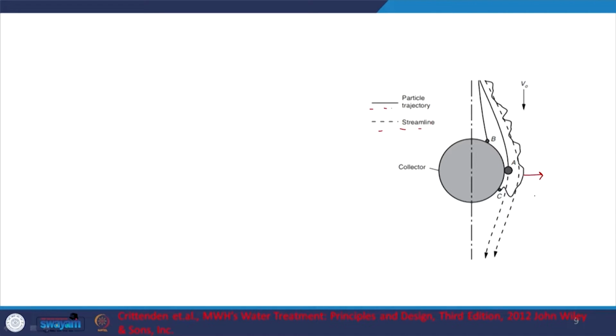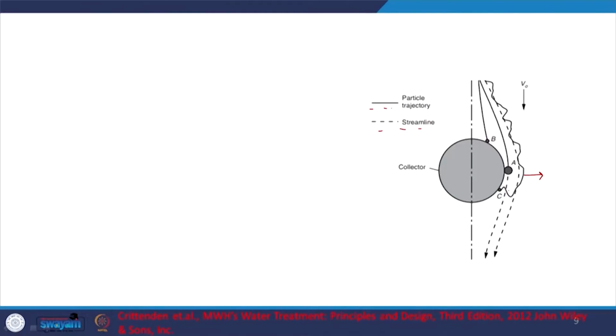As you can see, particles, typically smaller particles anyway, in the context of filtration, are going to have Brownian motion. Diffusion. So, in this random motion, the particles will come and be adsorbed by the relevant media. This is the media obviously, right. And what else? So, again interception, I guess, in a way. So, the water is taking the particle near the relevant media and then it is intercepted.